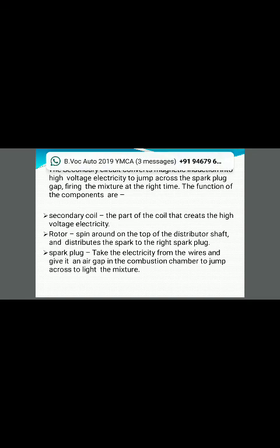Now we are going to discuss the secondary circuit. So what is the role of the secondary circuit in the battery ignition system? The secondary circuit converts magnetic induction into the high voltage electricity which jumps across the spark plug gap and fires the mixture at the right time.